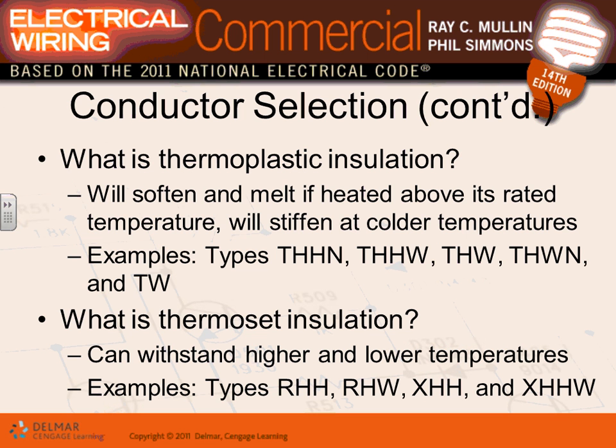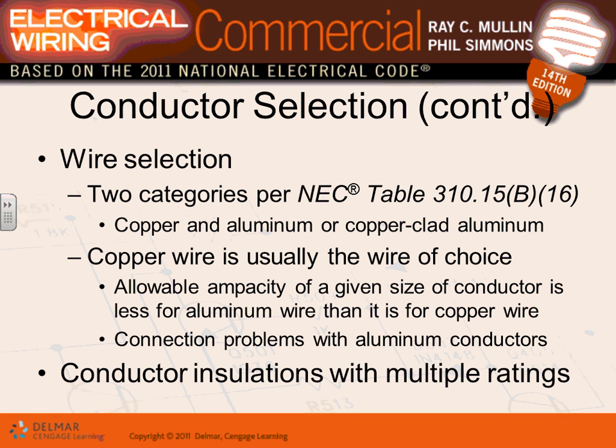Can I use RHH inside the building? Yes, you can, but you shouldn't. It's a little bit more expensive, right? It's a better conductor insulation, but not needed really, except for certain applications. So why do we use THHN? It's the most affordable, economical conductor that you can use indoor.